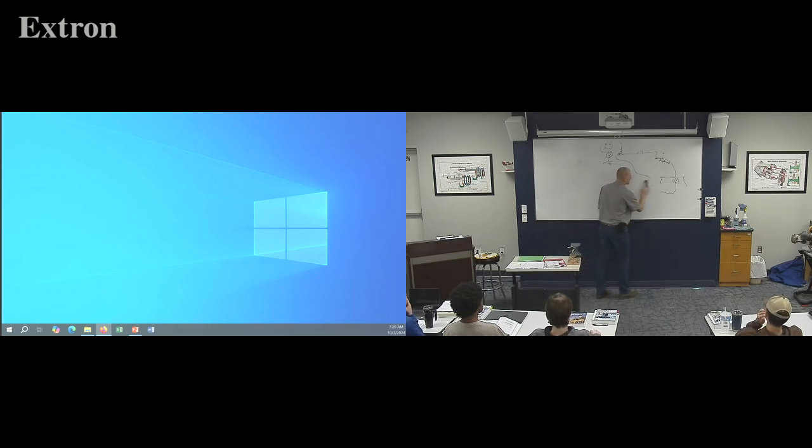Contacts on switches don't normally go bad, but when they do, they'll really give you grief, because every time you hit the switch, it remakes contact. And it's like, it worked that time, not that time. It worked that time, kind of works that time. So as you get deeper in electrical, if you're actually troubleshooting, there's a whole world of little funny stuff that can pop up at you. But that's how I would use it: just work your way through the process. Start at the beginning and work your way through until you go, ooh, I don't have voltage anymore. I must have a cut wire. I must have a bad switch or something to that effect.